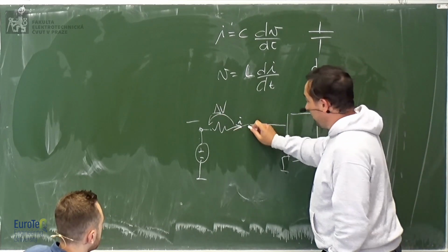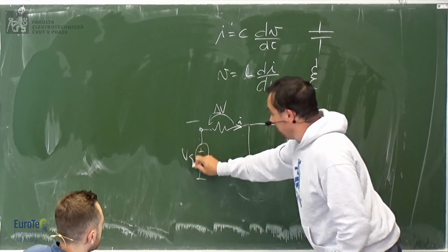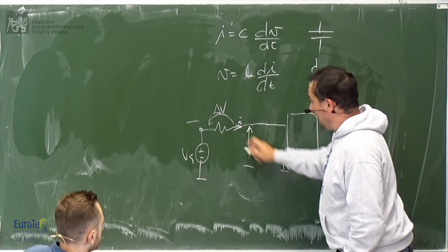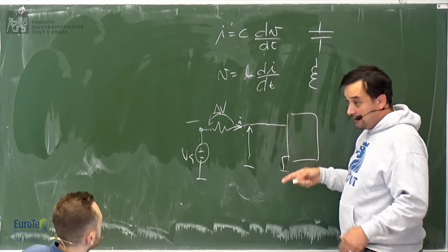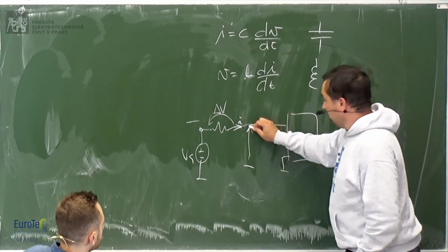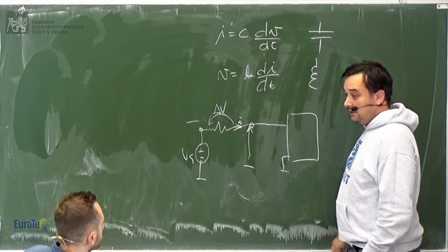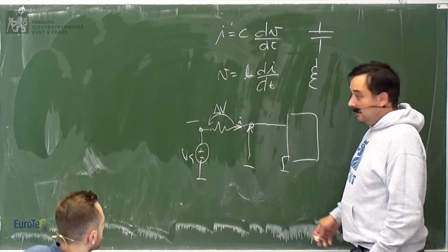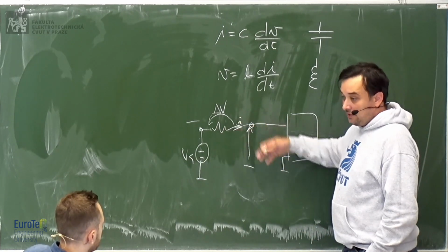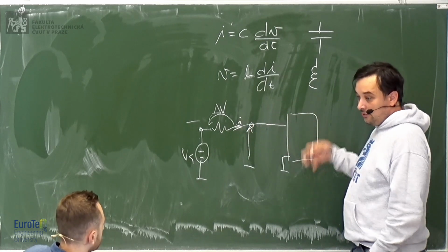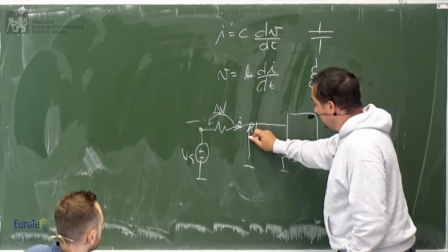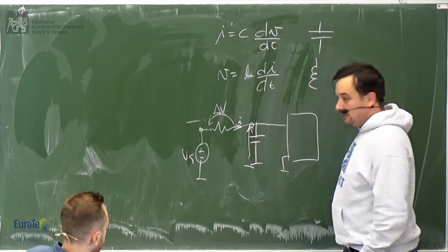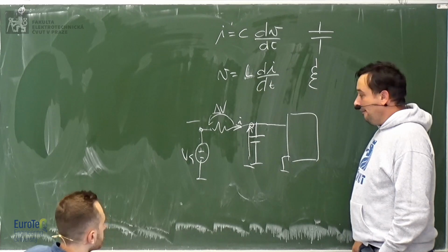So here you get the source voltage minus this voltage drop, which contains all these harmonics given by the current. But you want this voltage to be nice and clean, without the harmonics given by the circuit absorbing all this high frequency. So what you do, you put a capacitor, and we are happy about that.